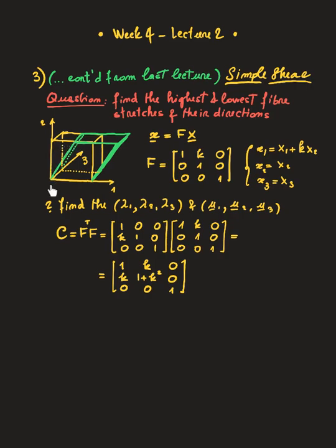This is the case for the base of this cube, but it's not the case for the height. You see, in doing the simple shear, the height, of course, remains the same, but this side is altered. So the edge, as you see, has a longer length. This is not the case when you do the pure shear, so the two states of deformation are different.